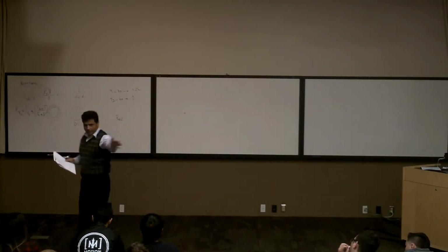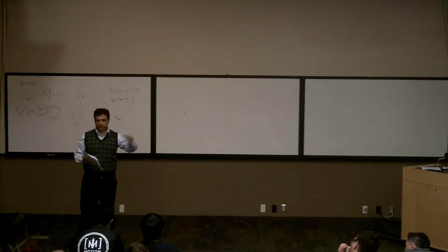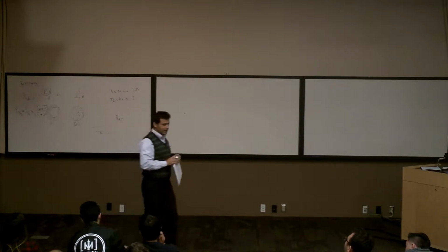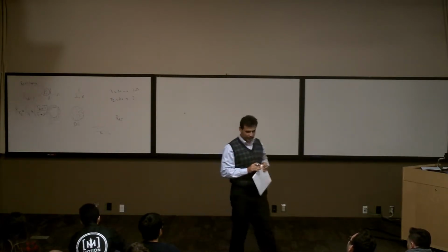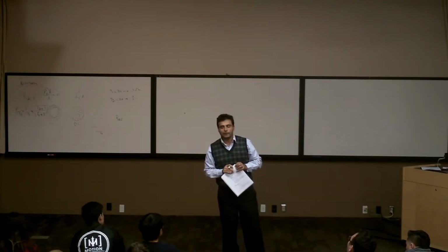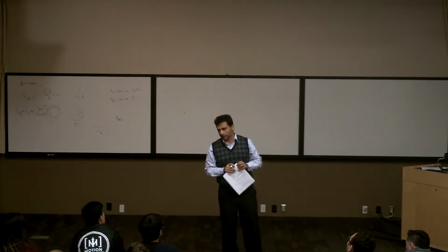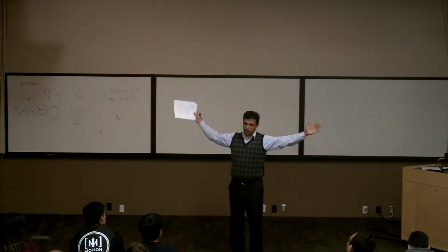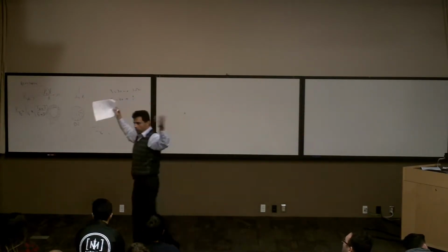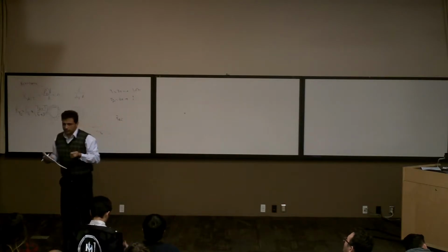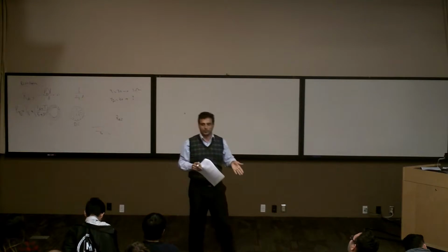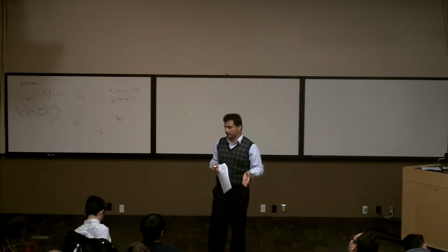But for most applications, what you guys have worked with is copper wire. But for transmission lines, they don't use copper. Can somebody tell me why? Too heavy? They are heavy, exactly. Think about it. There are these two towers, and these big cables, these wires, that are going to go between them. Copper is very heavy, so the weight of copper is going to cause a problem for the tower. They go with aluminum, right? It's much lighter than copper.